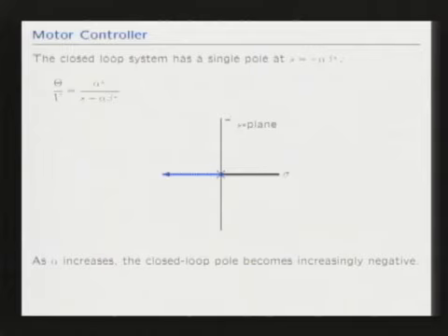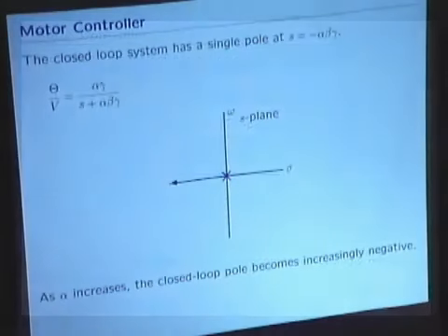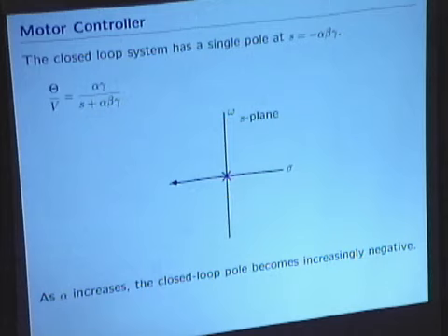Well, if the gain beta is 0, the pole is at 0. Okay, it works just like an integrator. That's what we said before. That's a sanity check, right? When you check something you already know the answer to, right? So if you set beta to 0, you get that the transformation is an integrator. Good. If you set beta to anything else, what happens?